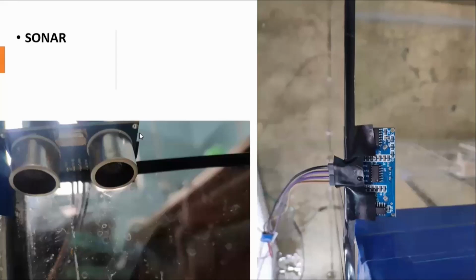Here is the sonar sensor. The working principle of sonar is pretty simple. It has a transmitter and a receiver. The transmitter sends an ultrasonic sound pulse and the receiver receives it. The sonar counts the time between sending and receiving. Then, using the velocity of sound in air, we can calculate the distance. We have used the HC-SR04 sonar sensor. It has 4 pins. The left one is the VCC, the right one is the ground, and the middle two are for triggering and receiving the echo.